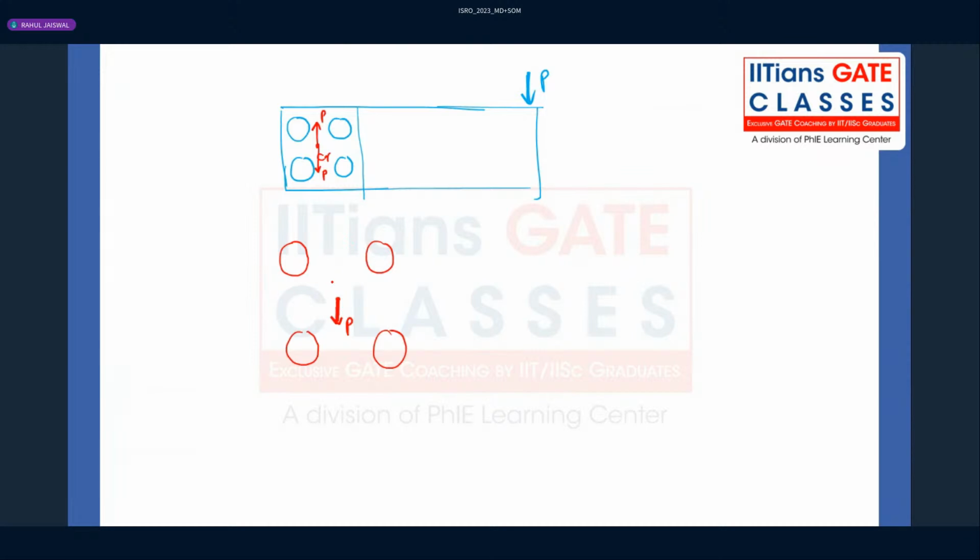Because when you transfer, there will be a twisting moment. Why not bending moment? Why twisting moment? Because the moment acting is parallel to the cross-sectional plane. The plane of the moment is the same plane in which the cross-sectional area of the rivets lies, right? So that's why we call this a twisting moment.